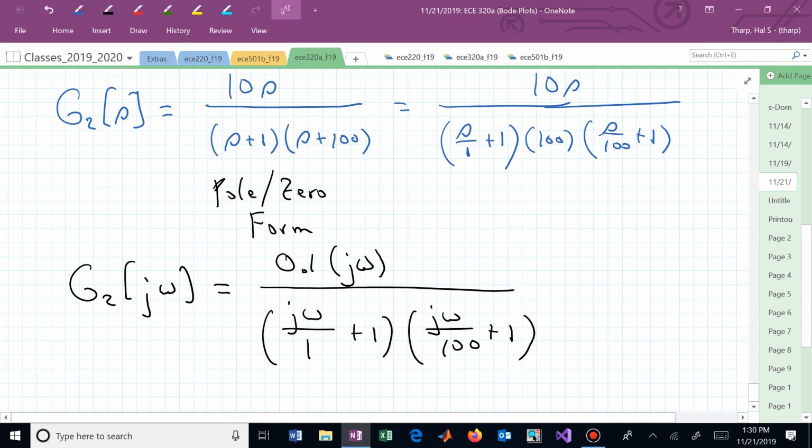What angle is that first pole factor contributing at 1,000? Omega equal to 1,000. That first pole factor, what angle is it contributing? Now get out your complex plane. If it's not making sense, you put a pole at -10 and you go, okay, I'm going to walk up the imaginary axis until I reach j1,000. What's the angle that that pole gives me? Oh, 90 degrees, but I'm downstairs. It's a -90.